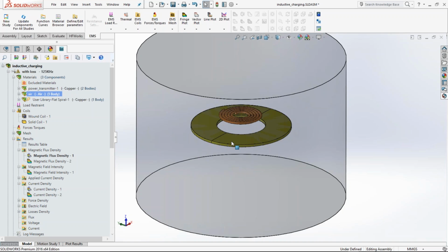Now one thing that needs to be explained here, this is more technical, is that you have to consider the air geometry big enough so that at the extremities of this air geometry, the field values are very small compared to the maximum field values, and the variations in the field at the air extremities are also small. So you have to make sure that you take the right size of the air box, and once you do that, we automatically enforce constraints on the outer geometry, the outer nodes, to take care of this.